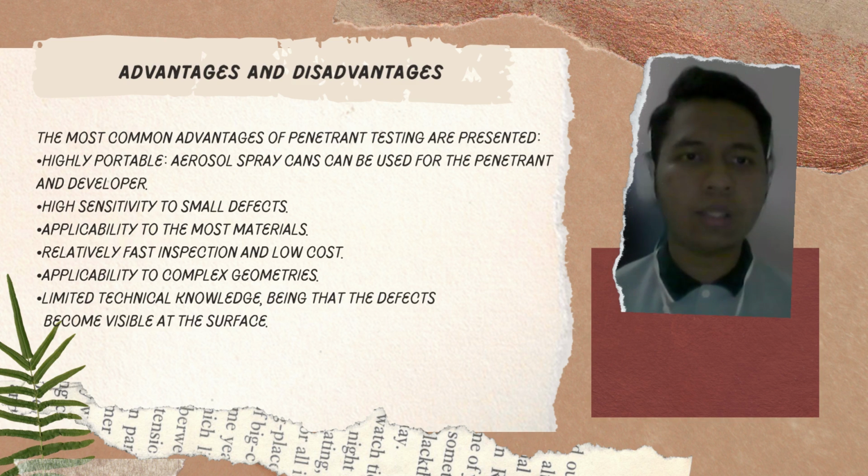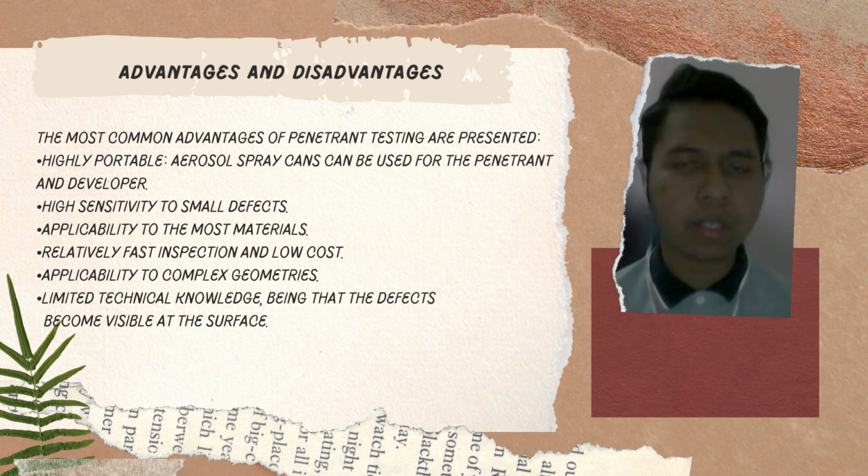Next, I will explain the advantages and disadvantages of liquid penetrant testing. The most common advantages of penetrant testing are presented. First, highly portable. Second, high sensitivity to small defects. Third, applicability to most materials. Fourth, relatively fast inspection and low cost. Fifth, applicability to complex geometries. And the last one is limited technical knowledge required, being that the defect becomes visible at the surface.